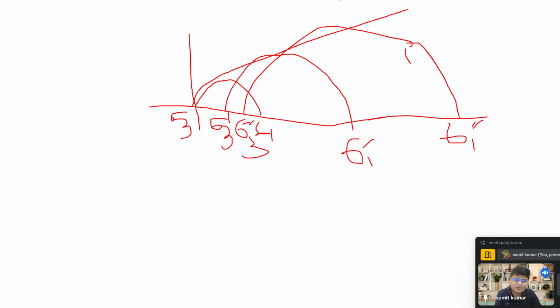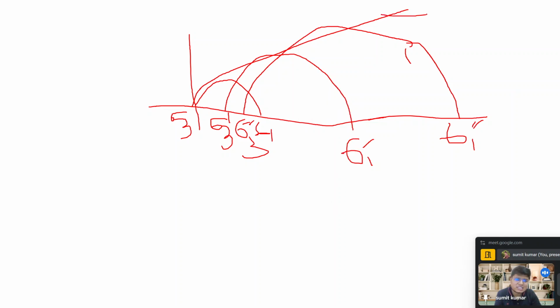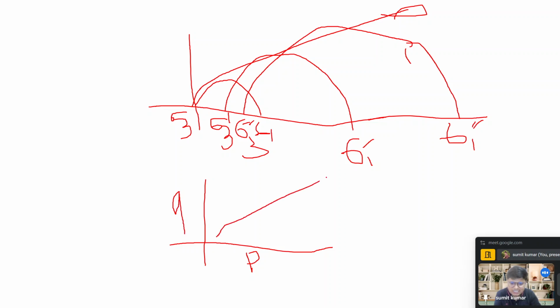This is the envelope line, below which it will be safe, and above that, it will fail. But when we draw the PQ curve, that is sigma 1 plus sigma 3 by 2 versus sigma 1 minus sigma 3 by 2, that line is going to be a straight line.